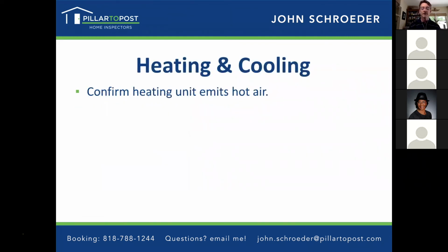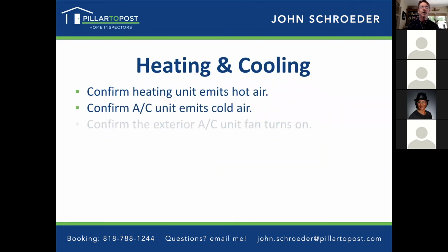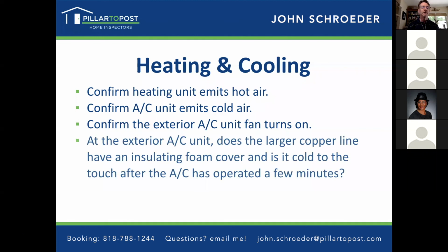For heating and cooling, you want to confirm that the heating unit emits hot air, that the AC emits cold air. A lot of this is pretty obvious, but it'll take some time and some effort to determine these things. Confirm that the AC condenser unit on the outside of the house turns on, the fan. There are refrigeration lines that run from that unit into the air handler, which is someplace inside the house. And the larger of the two copper lines should have an insulating foam cover and be cold to the touch when the AC has been running for a few minutes.